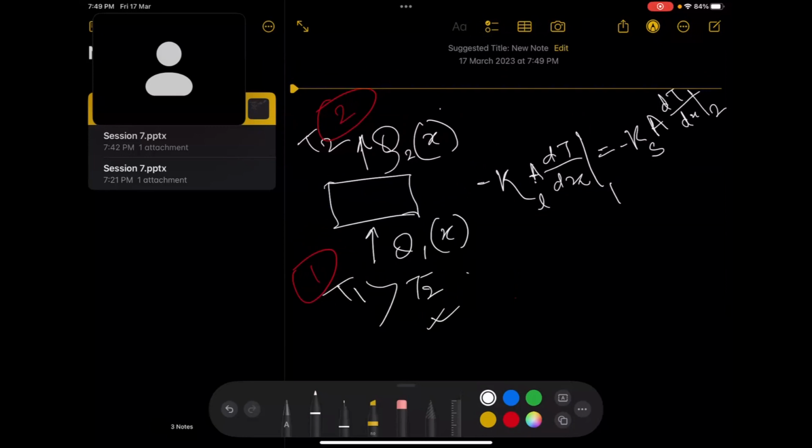Now if you do the heat balance, then what happens is the total heat transfer rate at the liquid metal side, subtracted from that on the other side, that is the crystal side, gives your latent heat multiplied by your rate, which is dm/dt.